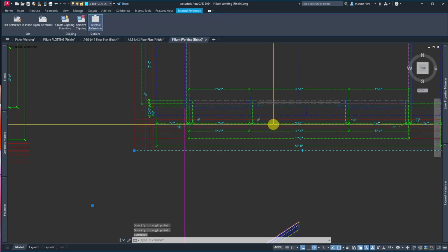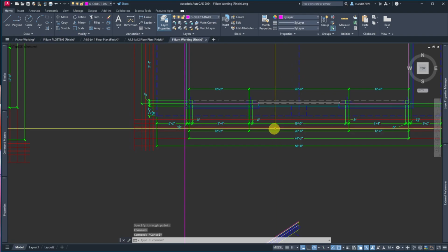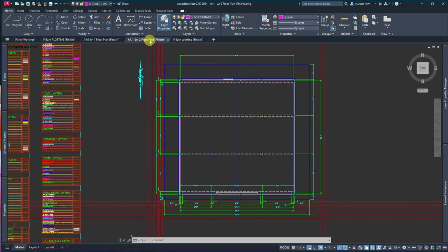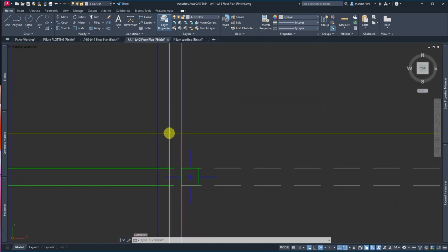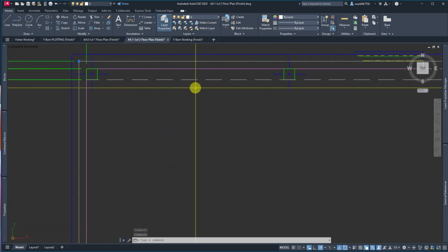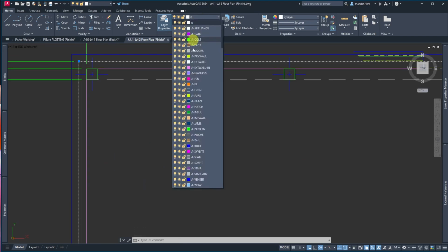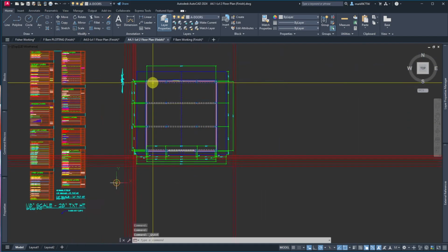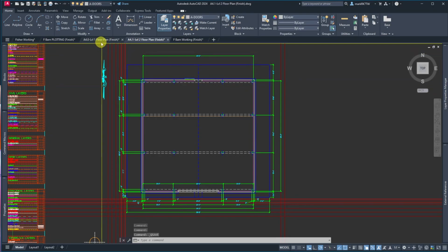This is on the wrong layer, I think. I don't know why that line turned blue. Oh, unless it's drawn on the 0 layer. Okay, so this should be the upper level. So if I come here, let's see if it's on the 0 layer. Yep, see that's on the 0 layer. So this exterior wall should be on an exterior wall layer. Then we hit save. It's the same color, so it fooled me. And since we had an issue there, let's save again.